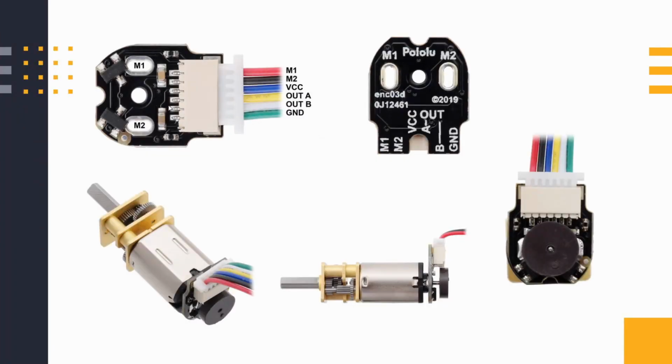And this is what the sensor we're going to be using looks like. As you can see, there are two Hall effect sensors here, and they're positioned right below the magnet. It's going to be attached to the shaft behind the brushed DC motor we're going to be using. So the encoder is going to go on the shaft first, and then you put in the magnet. And as that magnet rotates, these two Hall sensors will detect, okay, it's spinning this way, or it's spinning that way. Or it can say, okay, it's not spinning at all.